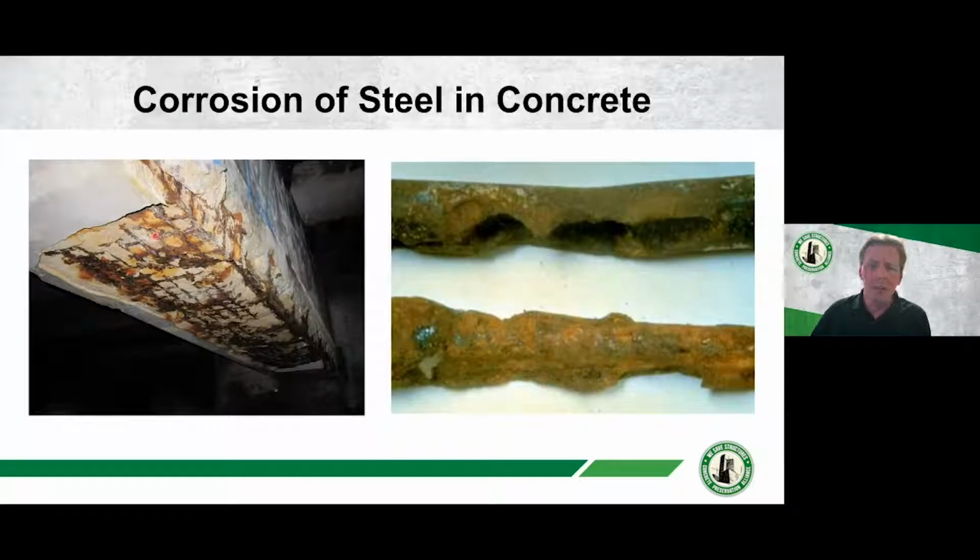As we see here, we've got widespread corrosion underneath the beam, spalling, cracking. It's looking really rough. And again, over here, we've got pitting due to chloride-induced corrosion. When the chlorides make it to the level of the rebar, it destroys the passivating layer over the rebar, that's a protective layer that the steel has in the concrete. As that breaks down because of the chloride ingress, corrosion occurs.